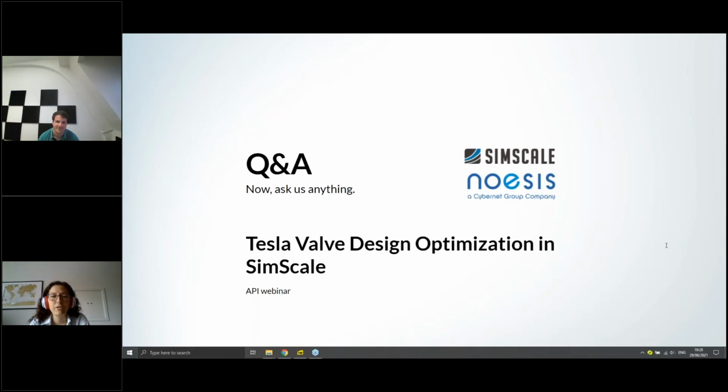Yeah, so from our side, the limits will be what makes sense for your algorithm, actually. So for sure, for the specific case, 2 jobs in parallel makes always sense. But for the multi-objective optimization we use, Optimus is learning from 16 populations. So running more than 16 cases at once doesn't really make sense. Optimus will wait only for the 16 populations. But from the Optimus point of view, it depends on your resources and what your algorithm expects.